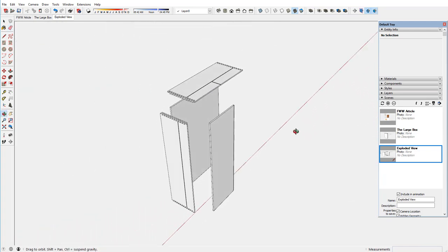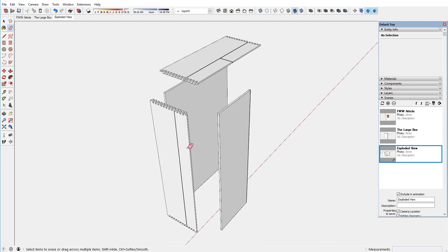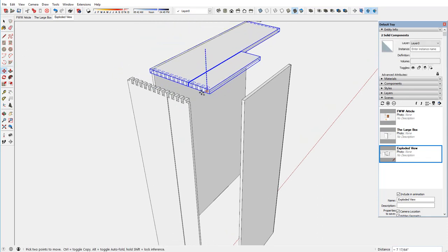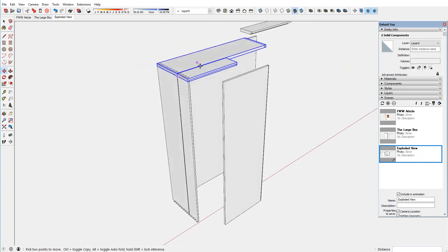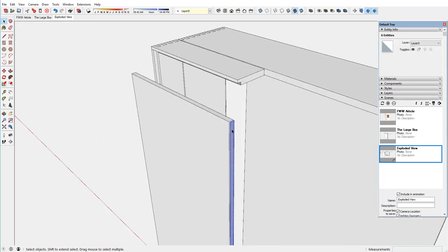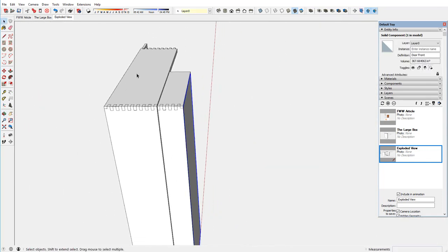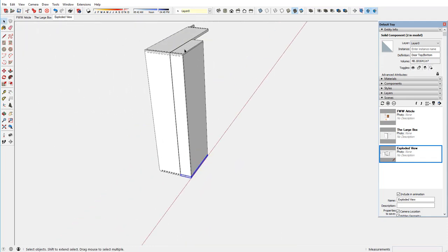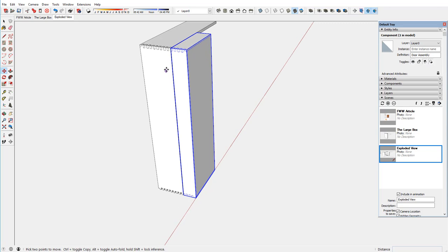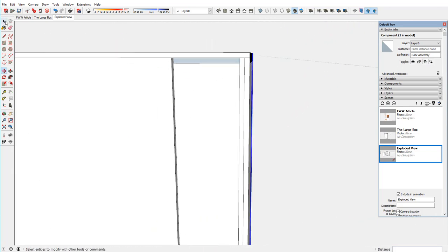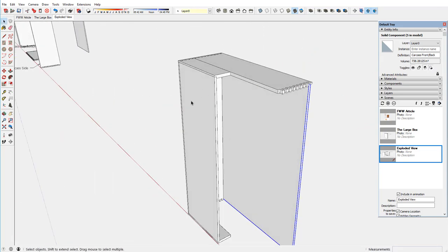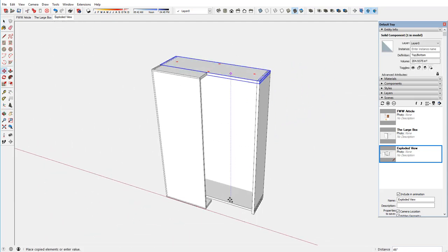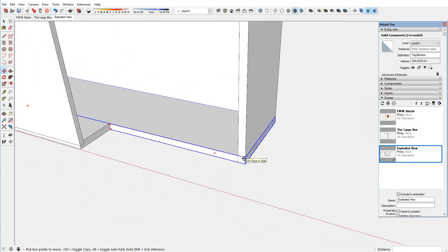Okay, so now I can put together the final cabinet parts. And I'll just speed up here a little bit to do these connections of the components. And the back panel, well, the bottom needs to be copied and flipped. And then I will make that a door assembly, taking those components and arranging them together. The back panel, copying the side and flipping, and the top, flipping it, making it the bottom.